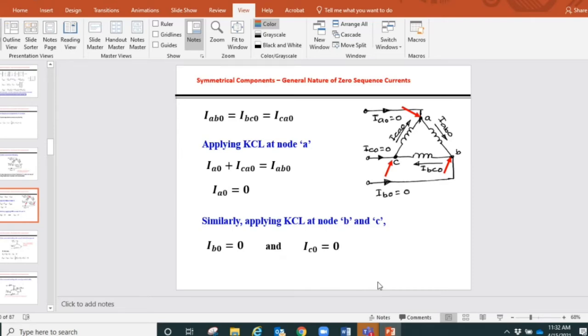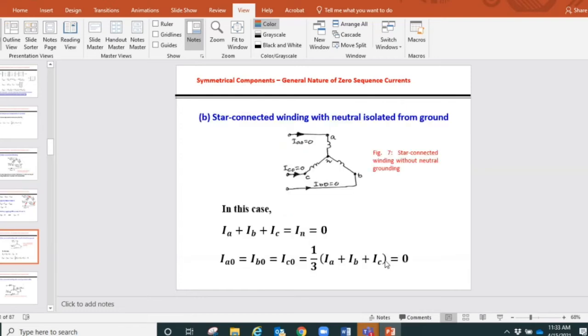So we'll remember this: when we have a delta connection, if the branch currents or phase currents inside the delta configuration are of equal magnitude, the line currents for the zero sequence will be 0. None of these phases A, B, C will have zero sequence current. We're talking only about zero sequence current, not positive or negative. They might be different. We'll have to remember that.